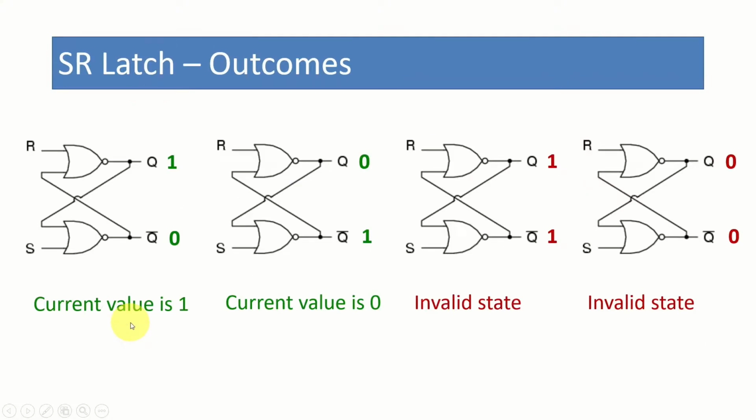And also when it comes to the SR latch, there are 2 possible outputs. If you have set it, the output must be 1. If you have reset it, when we read, the output must be 0. But you can see it's not just one output. There are 2 outputs. Actually, we are only interested in the first output. We call it Q. And Q bar is just a supporting output to have the functionality.